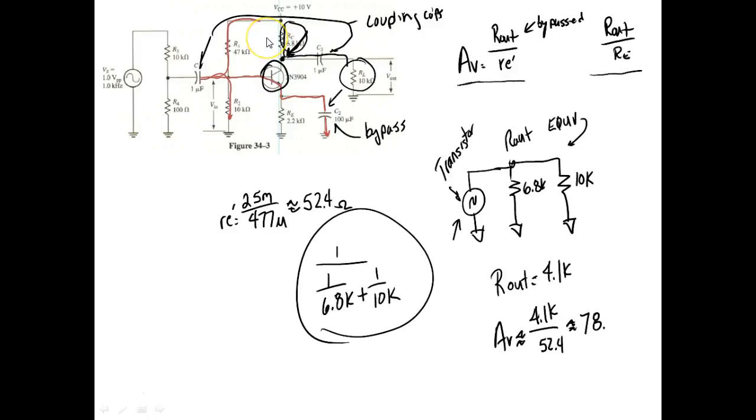How do we calculate gain? Any gain. What's gain? What'd you say, Courtney? Yeah, but how would we calculate it? That's exactly right, because gain is always out over in, no matter what. We're trying to do voltage gain. We measured 720 millivolts out, and we're putting 10 millivolts in. So our AV is going to be this right here. What's our AV?